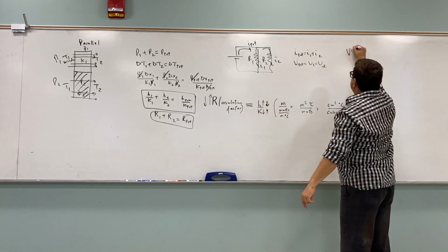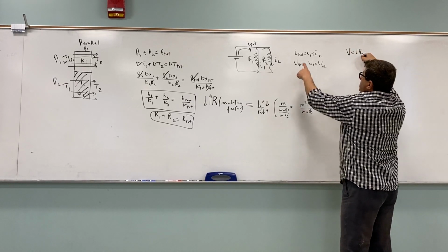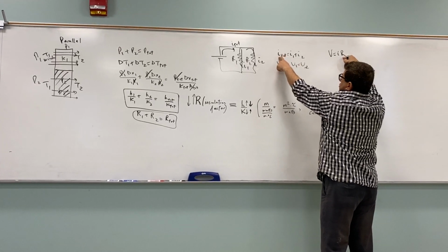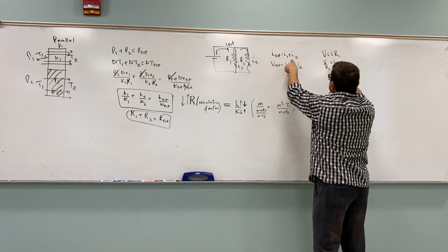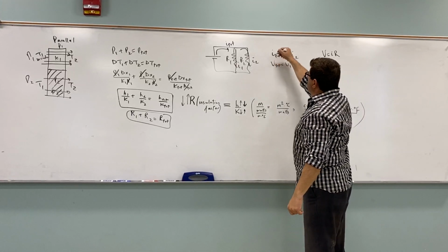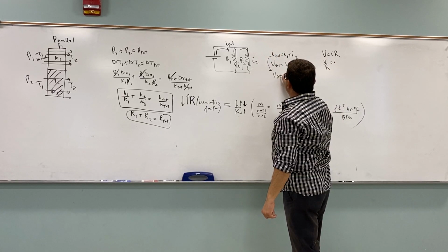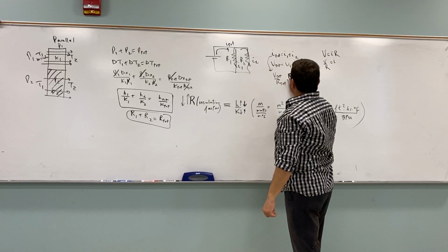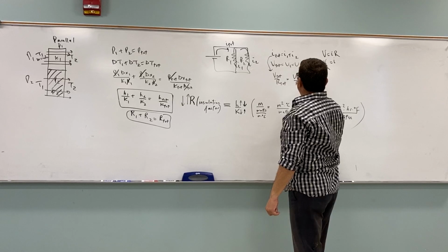Then you use the equation that connects voltage and resistance, and then you say, oh, which one adds up? So you look at the one that adds up, you solve for that variable, I is V over R, then you substitute, okay, therefore I total is equal to V total over R total, and that's equal to V1 over R1 plus V2 over R2.